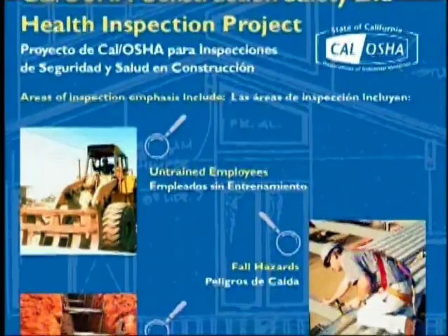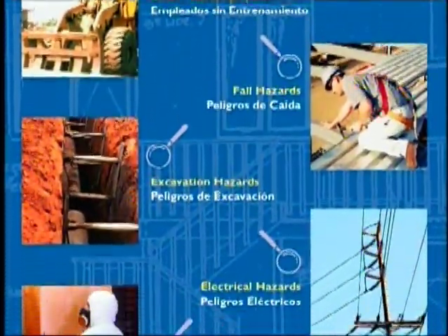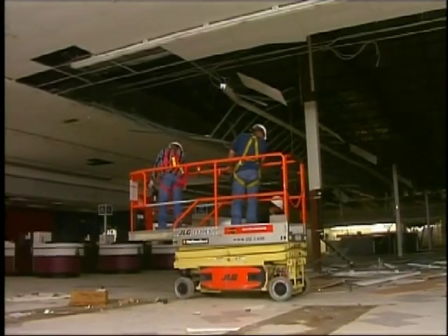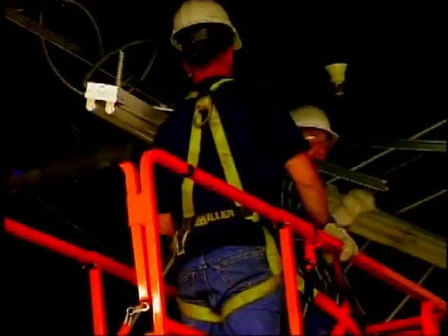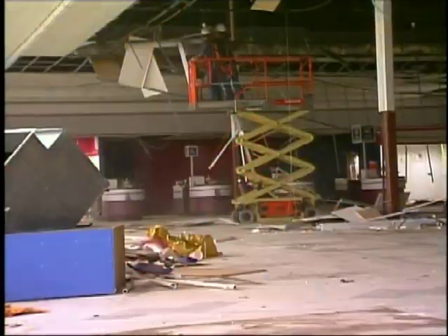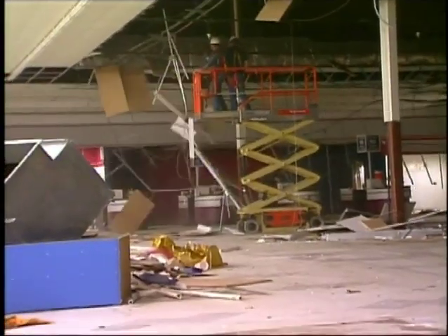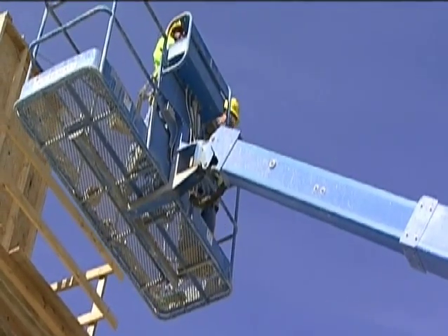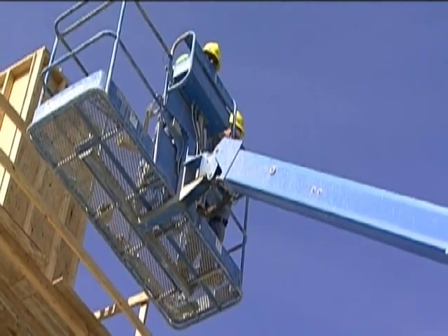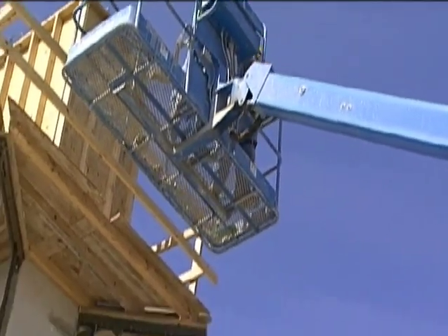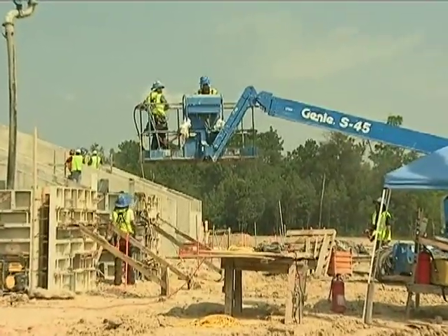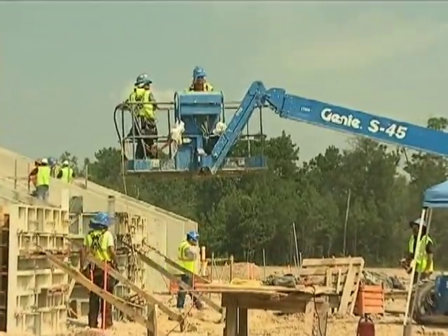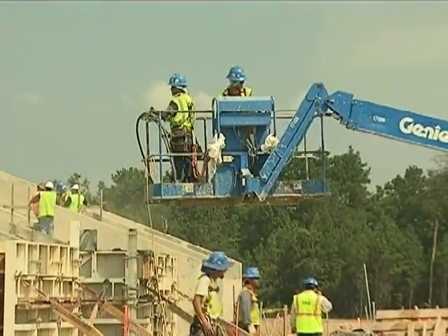Employers should also be aware of local and state regulations and ensure compliance with those laws. Only authorized and trained persons should operate an aerial lift. Never tie off to an adjacent pole, structure, or piece of equipment while working from a lift. Personnel should always stand firmly on the floor of the lift. Never sit or climb on the basket or guardrails, or use planks, ladders, or other items to attain a higher work position. If additional height is needed, then the lift should be extended, or if necessary, a different lift used that is appropriate for the job.